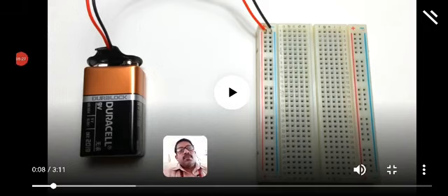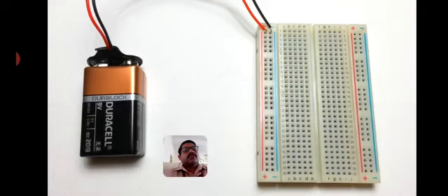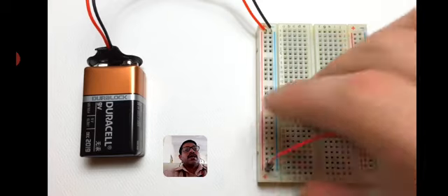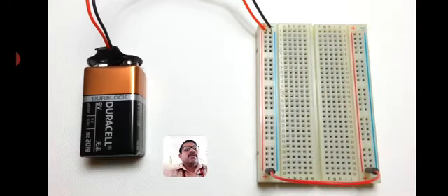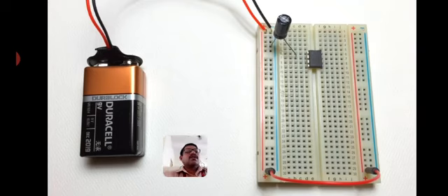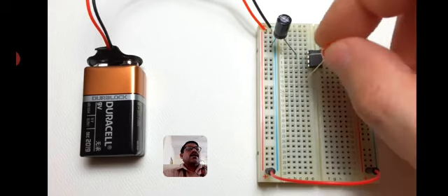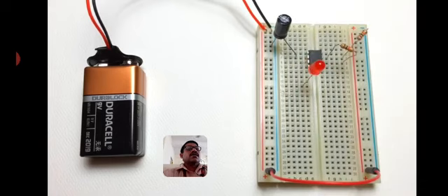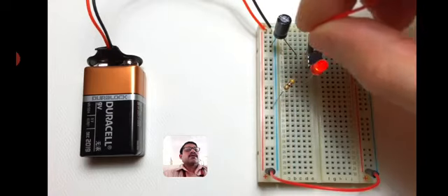Now this astable mode multivibrator circuit was given in a breadboard. Let me see it. This is a breadboard. On the left hand side is the supply. The connections are given. I think that you know the connections of a breadboard. See, the 555 timer IC is placed. The RC, the capacitance, the resistance values come into picture. Pin number 2, the capacitor is placed, and in pin number 7 a resistor comes into picture, and the LEDs, which are used for blinking lights.